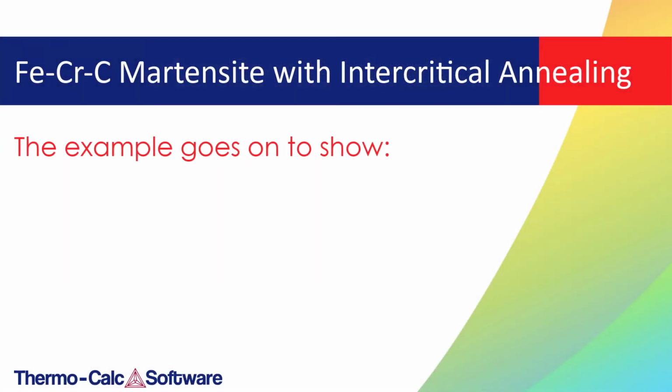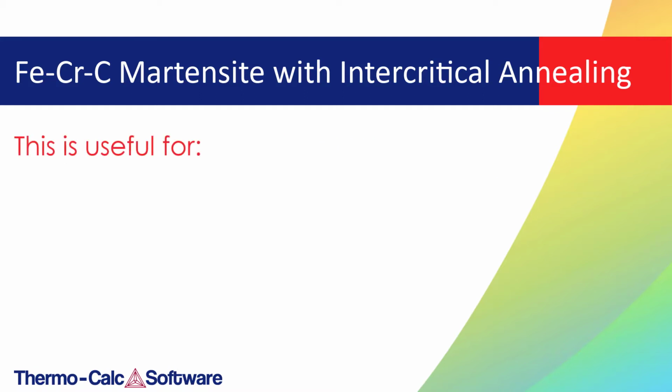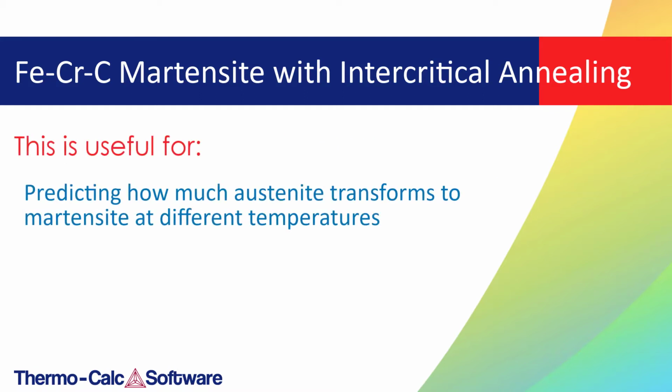The example goes on to show how to calculate how the chromium content in the alloy influences the Martensite start temperature and 90% transformation temperature, or M90, after intercritical annealing. This type of calculation is useful for predicting how much austenite transforms to Martensite at different temperatures.